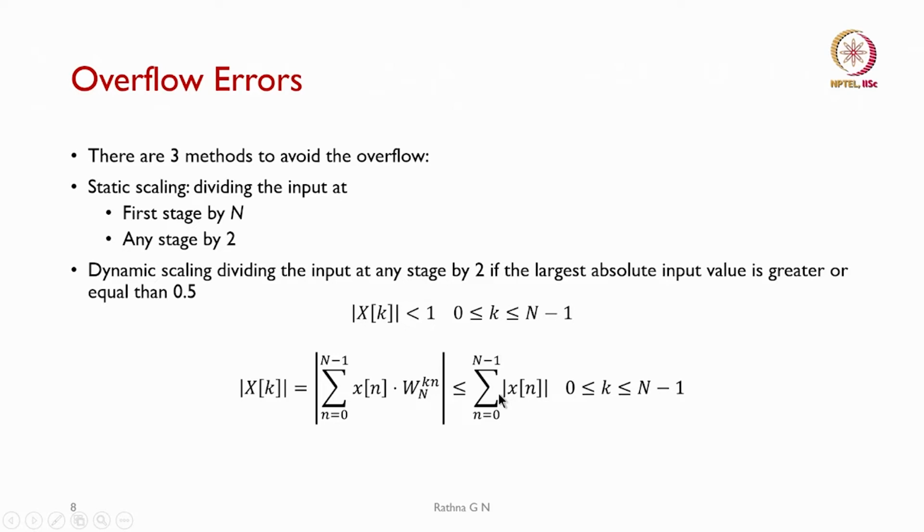Just like our FIR filters, if we have more than n minus 1 stages, the addition can be taken care of in our accumulator by having guard bits, and then later on we have to do the scaling.